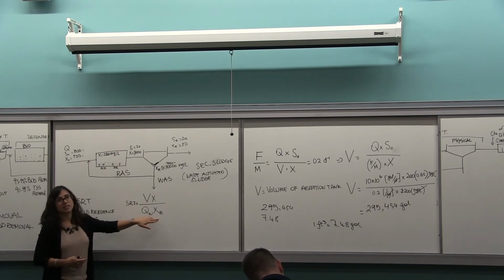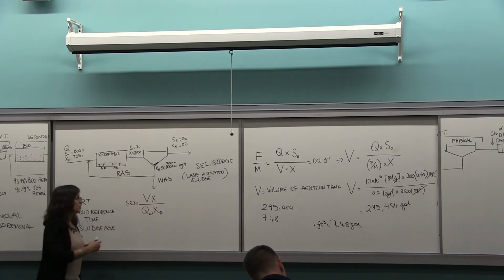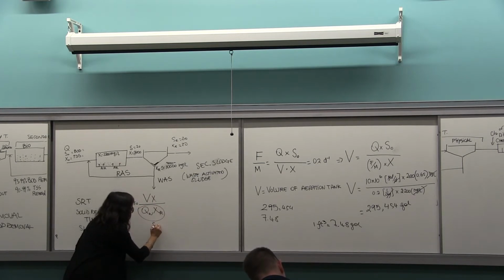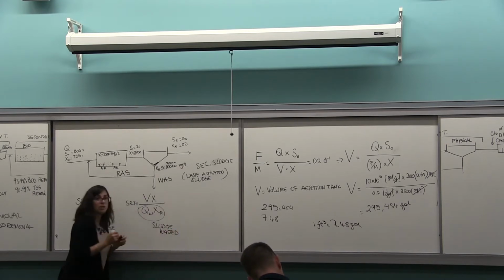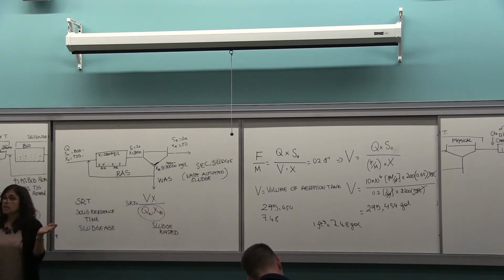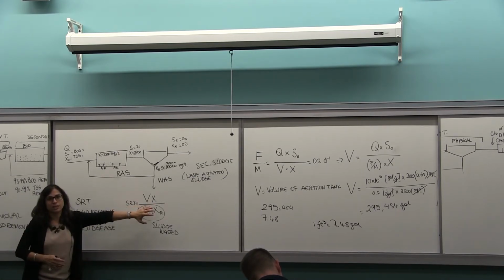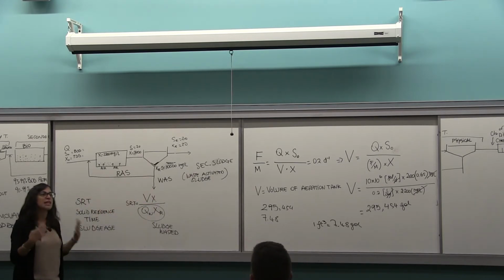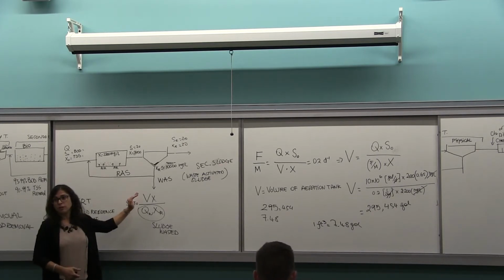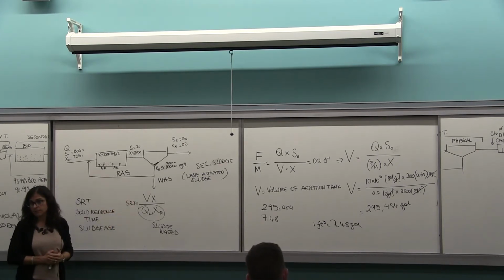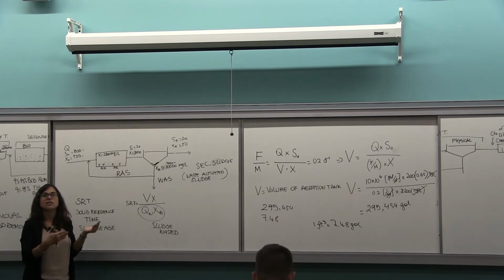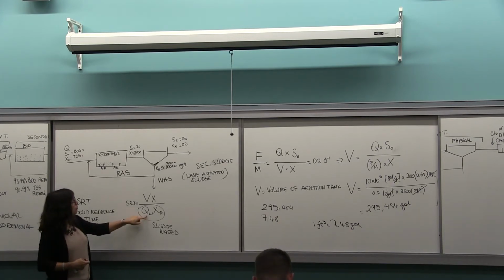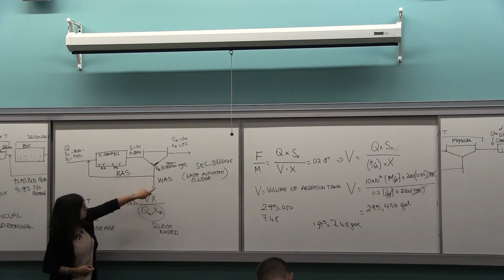Over here is the sludge that is wasted. Some problems will just give you the secondary sludge, say 300 kilograms per day. So pretty much you are given this. If the previous problem had also given you that secondary sludge, you could have determined the volume based on SRT. So it's another design. Or it could have given you the flow rate Q.